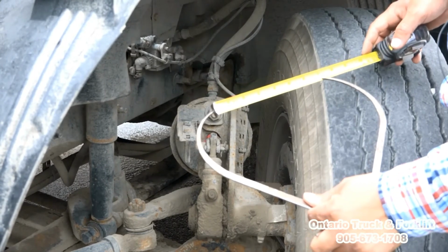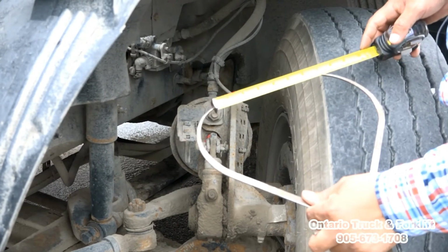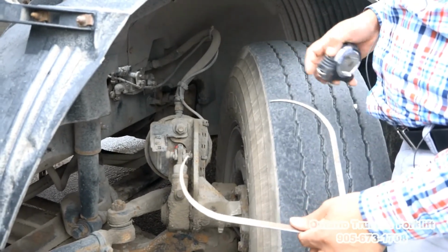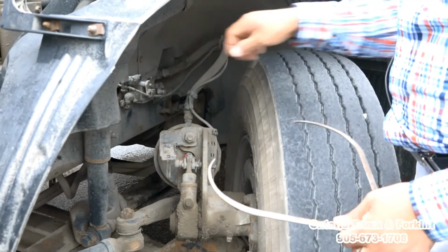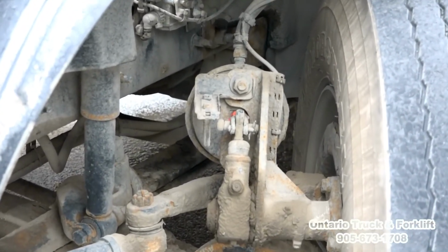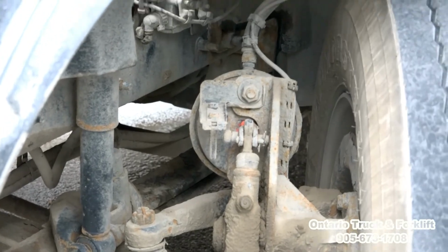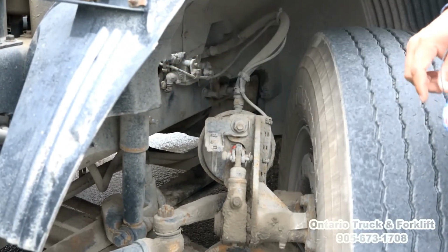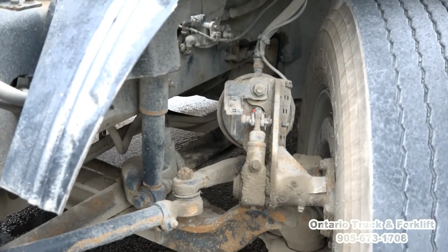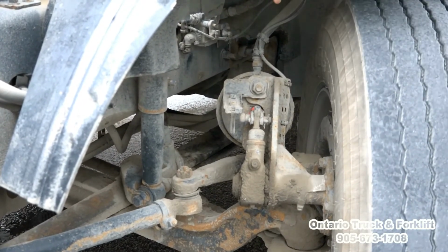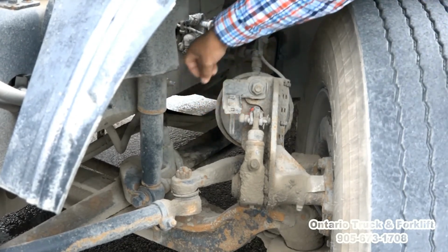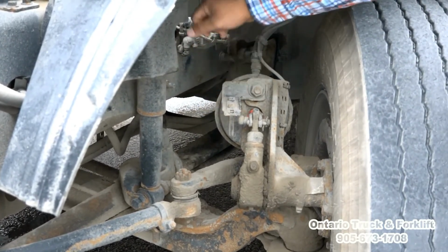Multiplied by 10, that becomes 175 millimeters. So the brake chamber size is a 20, because it's close to 172. And at the back side we have a tag that tells us this is a 20L size. Now we have to put a mark on the push rod. We already have a permanent mark there.